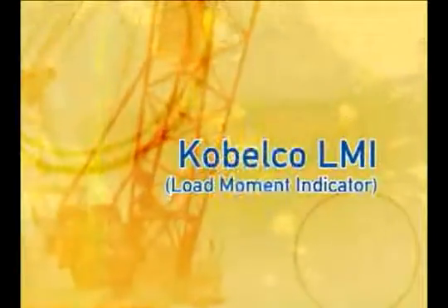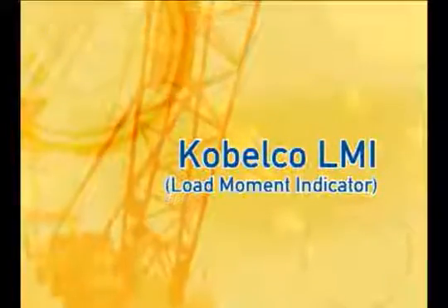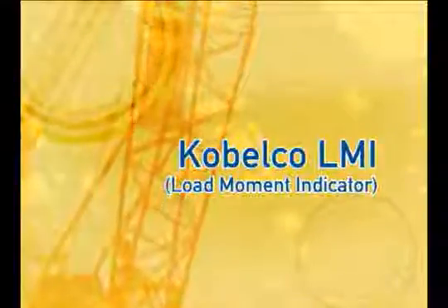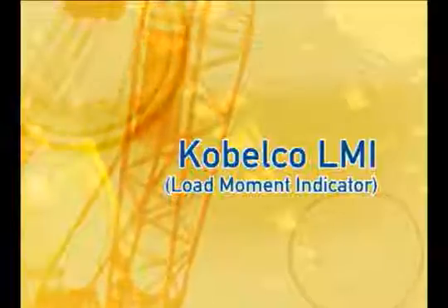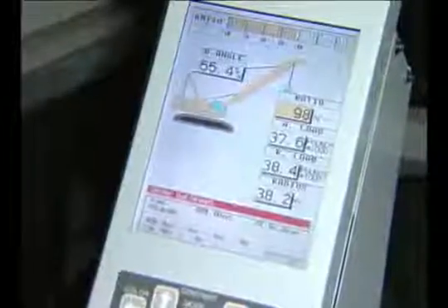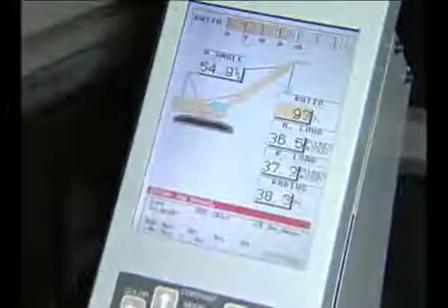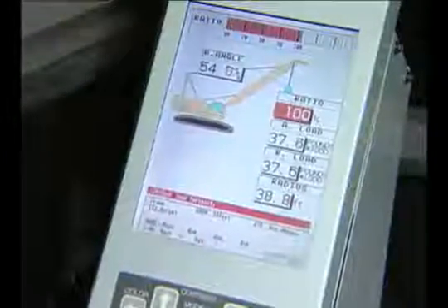In this section, we will cover the Kobelco LMI, Load Moment Indicator, that is designed and built by Kobelco as an integral part of the crane's design. This system provides audio and visual signals as the load or the radius approaches maximum limit and stops crane functions when the limit is reached.